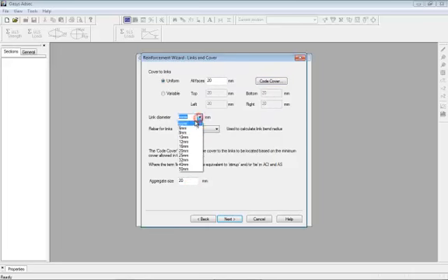Cover links. Now note that the links are there not to calculate shear reinforcement, because shear is a three-dimensional phenomenon, whereas this is purely a cross section. But they are there to position the main bars.